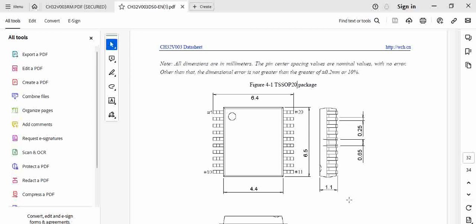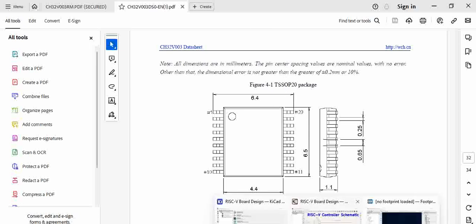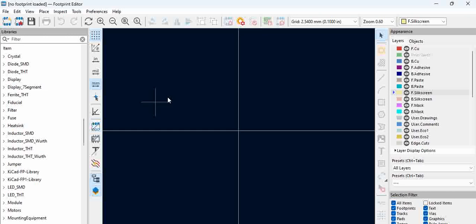In many cases, very simple problems happen where the manufacturing part number and the footprint vary. We might consider a footprint of a QFN part, and then order a TSSOP part. This is a common mistake that happens in the schematic. To eliminate that, first we have to ensure MPN versus footprint. So we have a TSSOP package in our schematic, and then we are creating the footprint.